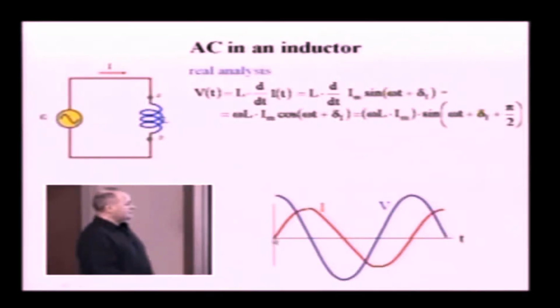So how about if we look at it? Let's say I consider this instant. What is the phase of the voltage? Voltage is the blue, represented by the blue plot. What is the phase of the voltage at instant 0 here? Oscar? It isn't negative pi over 2, it's just pi over 2, right? The value is 1. I mean, the highest value, right? So it means the phase, the argument of this sine function at t equals 0 is pi over 2.